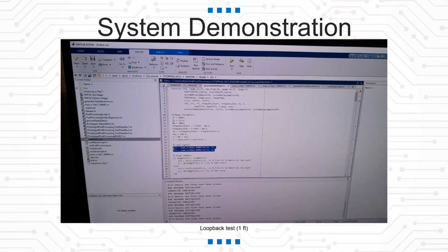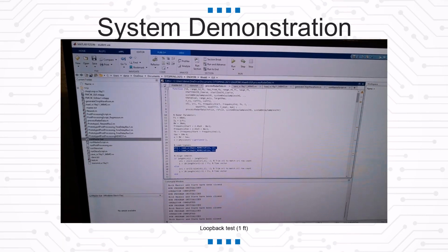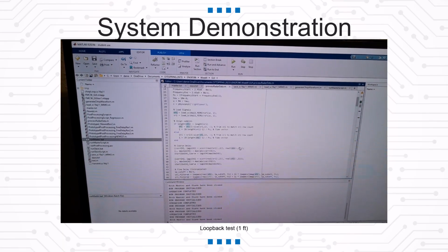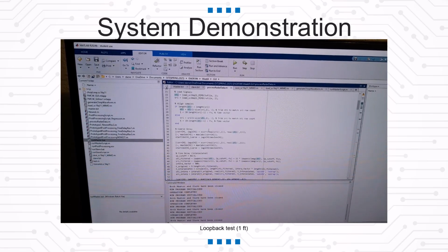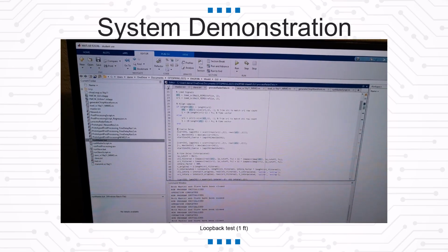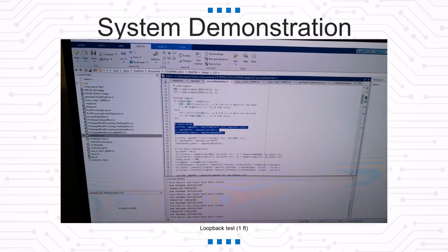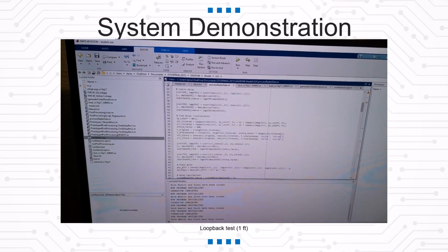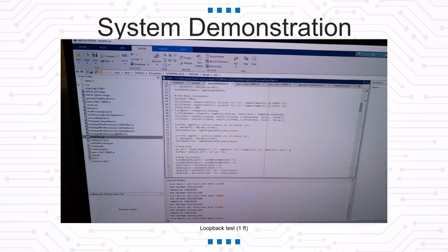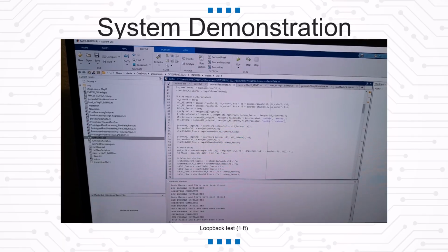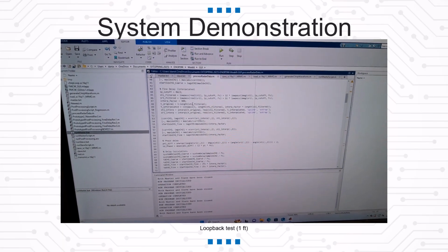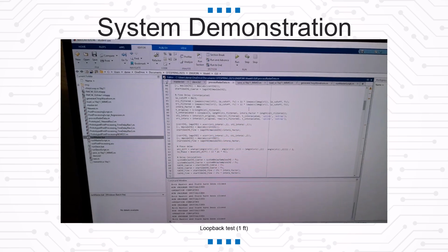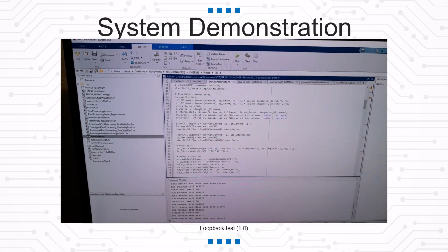It loads the signals and saves them to variables. We do cross correlation of the signals to get the time delay, and then we do upsampling using interpolation to get a higher resolution time delay sample.